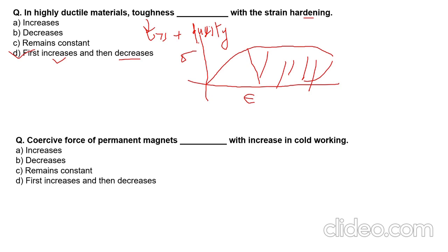Yeah, but even if you have a normal ductile material, it depends. For example, what kind of interstitials are there? In a steel, as you are saying, you can have some interstitial spacings. The effect of your grain size also comes into play. Your post heat treatment methods will also play a role. So the system is becoming complex, and you cannot clearly say for such systems.